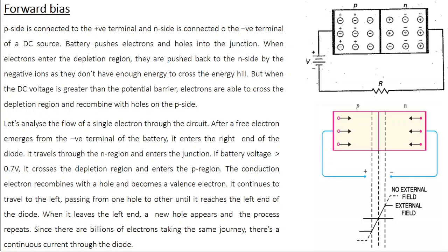You increase the forward bias slightly more, make it 0.2, but it is still less than the barrier potential. 0.3. Finally, you reach 0.7 volt. So you have 0.7 volt pushing the electron in the forward direction, but the barrier potential of 0.7 volt pushes the electron back in the reverse direction. Both these forces cancel. Once again, there is no current.